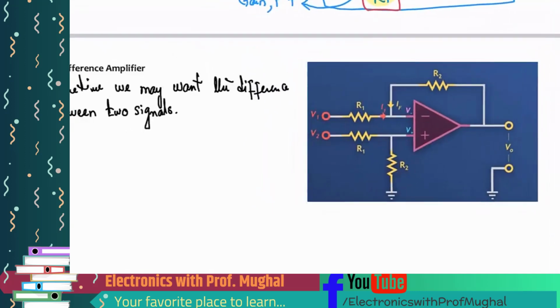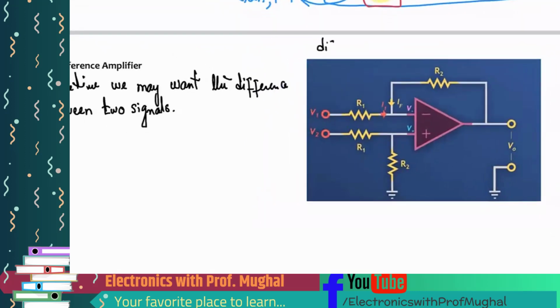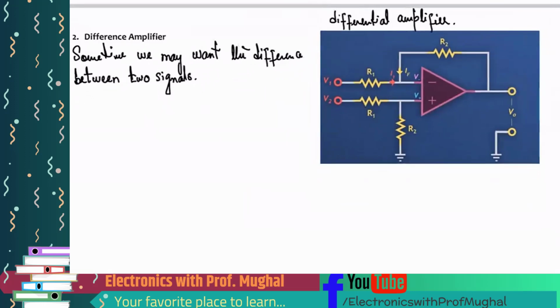Now, one thing that we learned on Thursday was the differential amplifier, right? Is this a differential amplifier here, folks? If yes, then how? Anybody recall the differential amplifier? A differential amplifier is an amplifier where you have both terminals of the op-amp, in this case both the negative terminal and the positive terminal, connected to an input signal, not a power source, sorry.